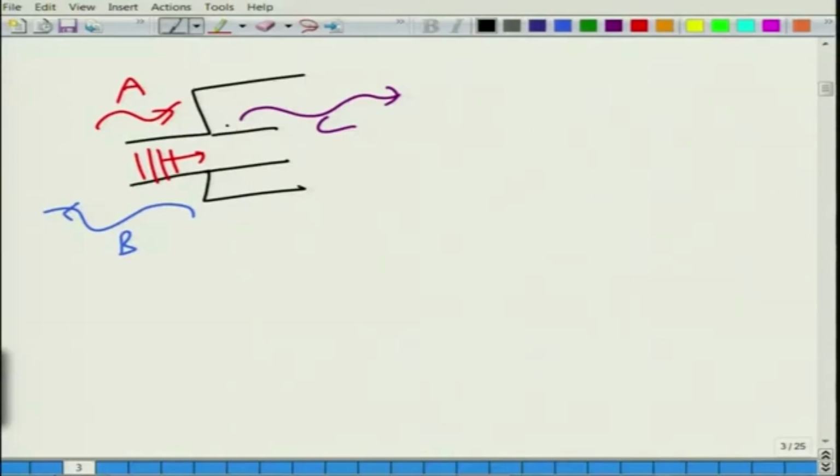By putting 0 impedance at the interface of this resonator and some finite impedance here, we saw that the waves choose to go towards the path of least impedance. So, they go in the side branch and less amount of acoustic power is transmitted downstream. The entire idea behind all such things is to continuously reflect the acoustic power or divert the path of acoustic power from the main propagation direction.